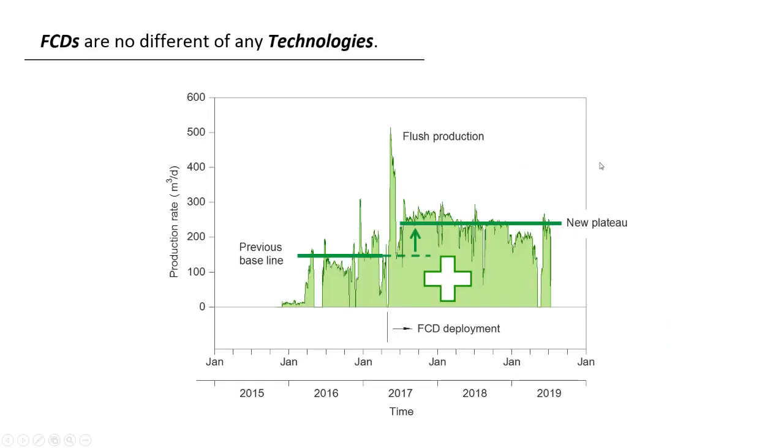The importance of modern liquid pool modeling at the current time is that a lot of operators have been using FCDs, flow control devices, for their operations. The problem is that if we don't have proper software to model these things, and we're not capturing all the phenomena, like going into the liquid pool and near-wellbore flashing, then we may come to the wrong conclusions and wrong designs.